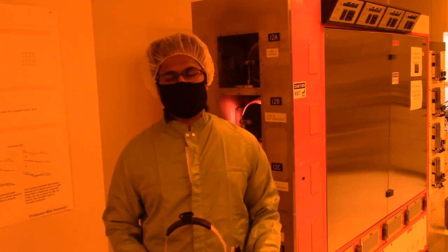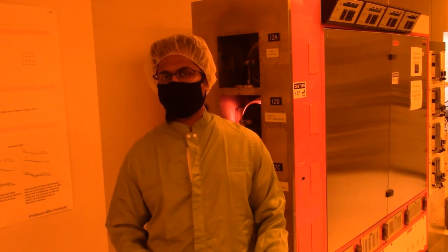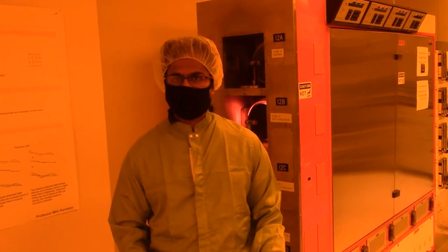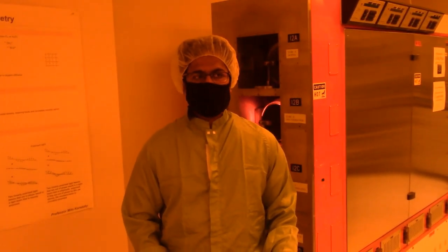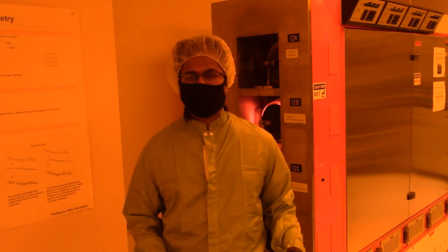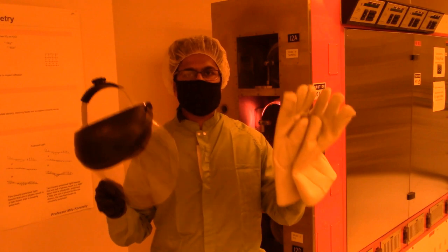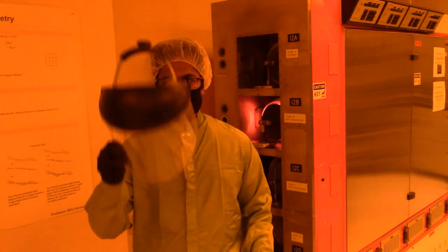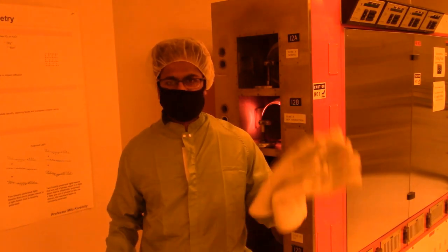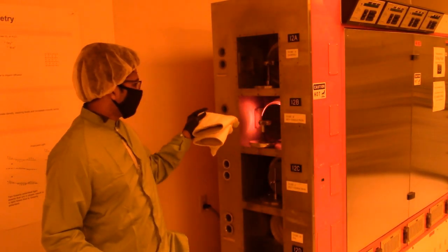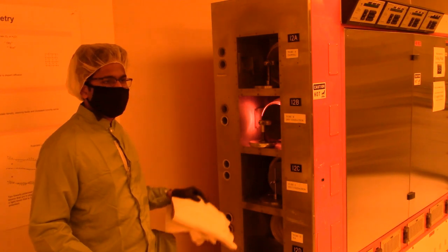Okay, now that the furnace has reached the temperature of around 1100 C, where we want it to be, we can go ahead and start loading our silicon wafer for growing dry oxide. Now that the oxygen has also been turned on, we need to make sure that we put on the personal protective equipment necessary to handle the high temperatures. The PPE required for this step is a face shield, as you can see over here, and jute gloves, which are the first order of protection from handling the high temperatures. You're actually loading in the quartz wafer boat into the furnace.